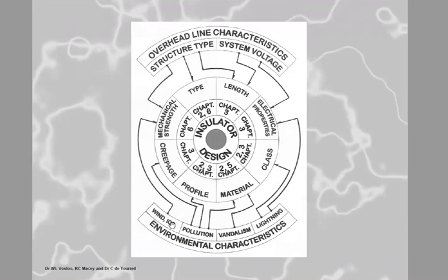And then obviously, believe it or not, in Africa we've got ice and snow loading. And so that all will influence your mechanical strength. The wind will influence your mechanical strength, and the ice loading. I mean, in Sweden, you can get up to 1 meter diameter ice on a conductor. Can you imagine the weight? Okay. I don't know if you guys have got that.